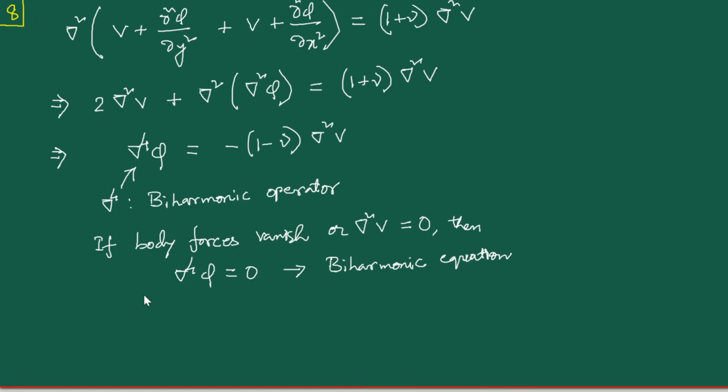Hello everyone. In the previous two lectures, we had been talking about one paradigm of 2D elasticity, which was plane stress, and we went on to discuss the Airy stress function approach and ended up at the end of those discussions with this biharmonic equation, which included within it almost all the information conveyed by the compatibility equation, the constitutive law, and the stress equilibrium equations.